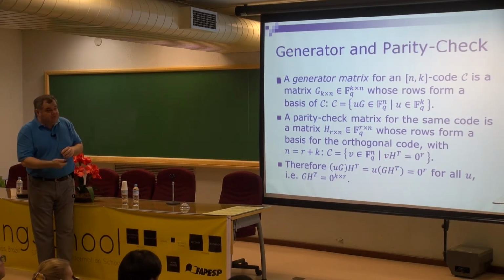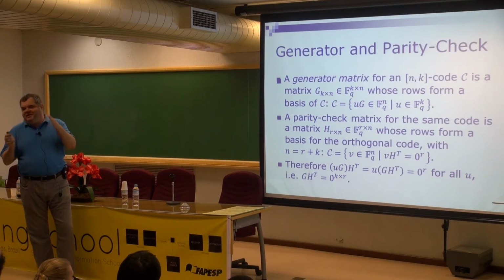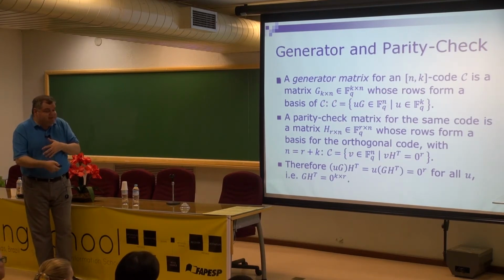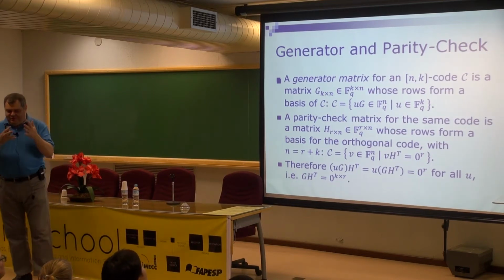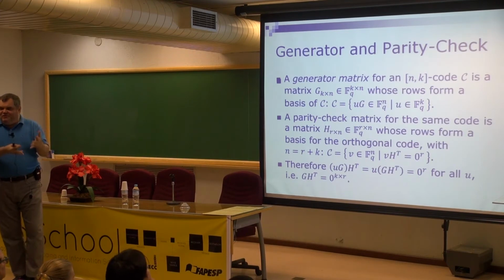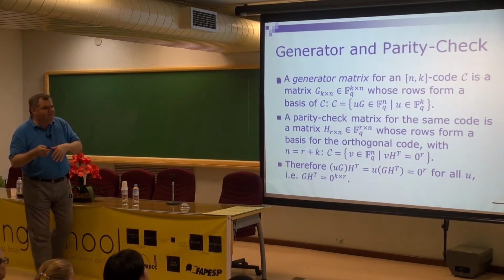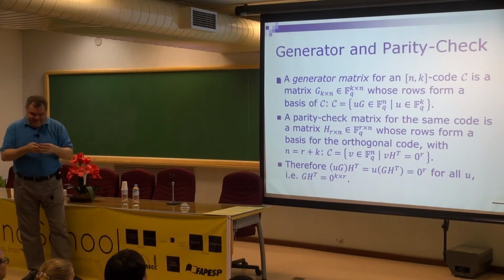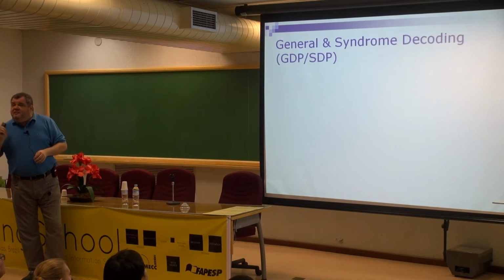If it is not 0, we probably are dealing with a code word with errors. If there are not too many errors, we can usually correct them. A syndrome is how we call the projection of a certain vector onto the dual code. But you know that, I'm only recapping the subject.